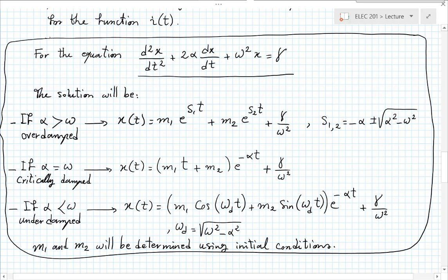If, on the other hand, we were in the case of the underdamped solution, alpha less than omega, then look at this frequency omega sub d, which is just the square root of a positive number. So that's just a positive number itself. And so your solution is in the form of a sine and cosine, so two oscillating functions that will oscillate for as long as you want.